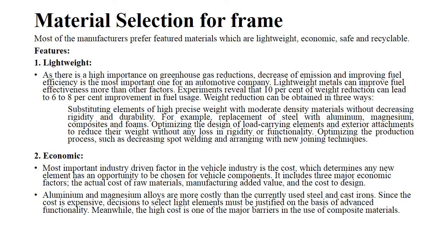Next we'll talk about the material selection for the frame. The basic criteria are that the material has to be lightweight, economic, safe and recyclable. Why lightweight? We need to decrease the emissions going into the environment, and only light metals can improve the fuel efficiency. That's the reason why we need lightweight materials.